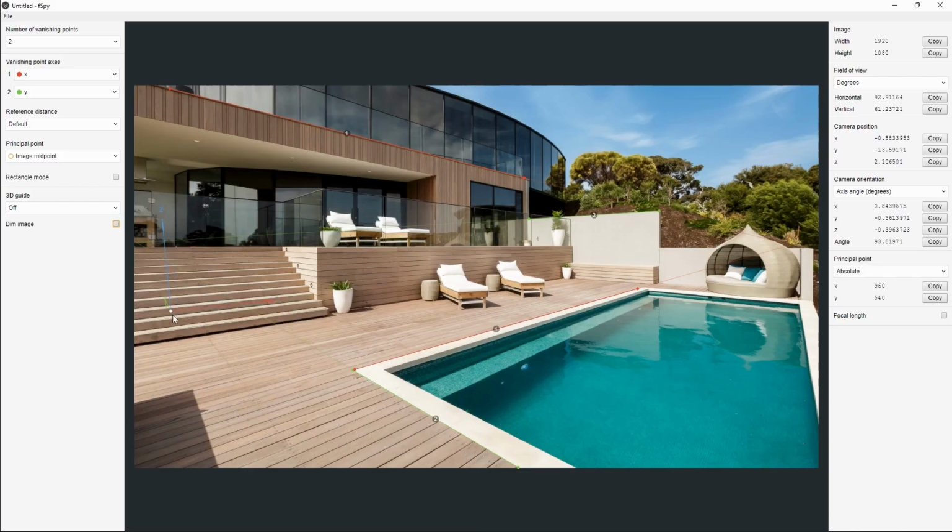Unfortunately, our z-axis doesn't align well. Apparently, this image has been cropped, so we have to switch to manual mode and locate the principal point ourselves. I know it's tempting to use this automated discovery mode from third vanishing point, but although this option is visible, don't choose it. This is not going to work this time because we don't have the third vanishing point. So we have to stick to manual and do something.